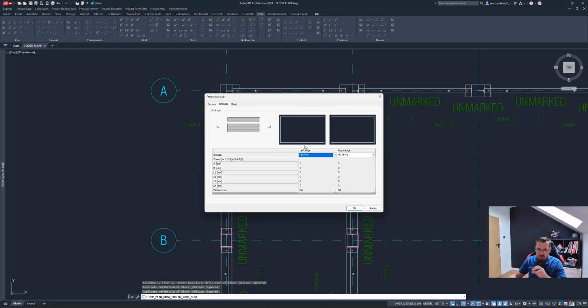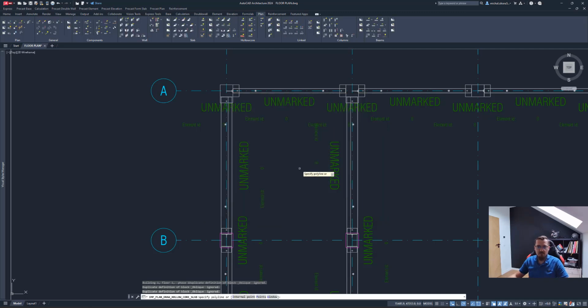End caps, in the end cap section we can go ahead and specify the end caps. By default it's the R1 defined in our standard, or L, which basically is a straight edge. That's it. But for example, let's go with something that we have, HD19U2 as an end cap, which is this nice little rounded cutout. Sorry, let's go and select that too. If you want to add more detail, like a recess or a cutout in the hollow core, then you can of course go by this preview image and add something here of your own choosing. And let us do that now.